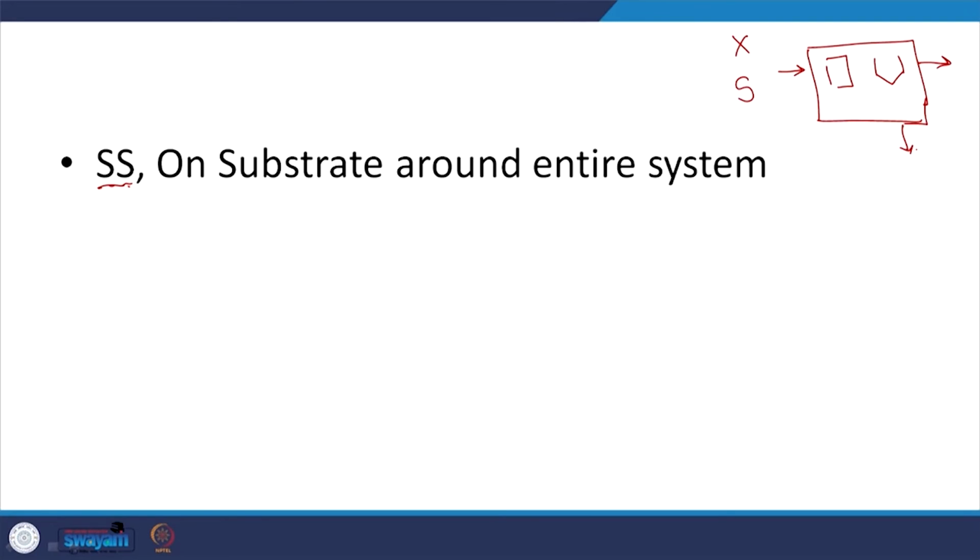Again, it is a CSTR, that is the assumption. Here again we are assuming that the reaction is only taking place in the aeration tank, it is not taking place in the clarifier. That is a good enough assumption because oxygen is only being provided here and no oxygen is being provided in the secondary clarifier. So, when we take the volume, effectively we need to take the volume of the aeration tank only, that is something to keep in mind.